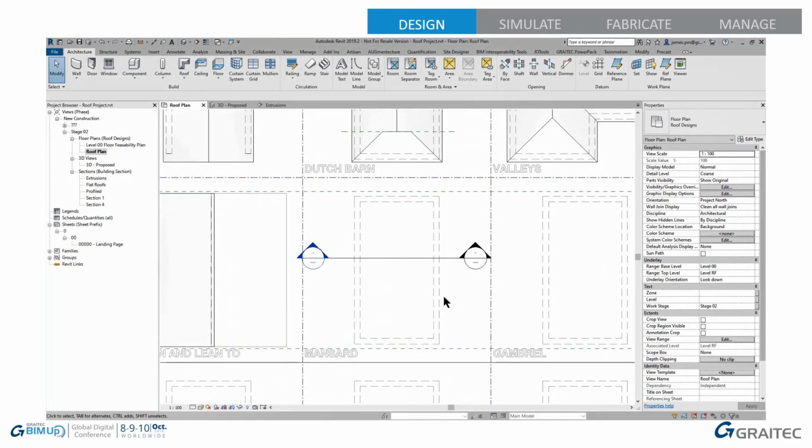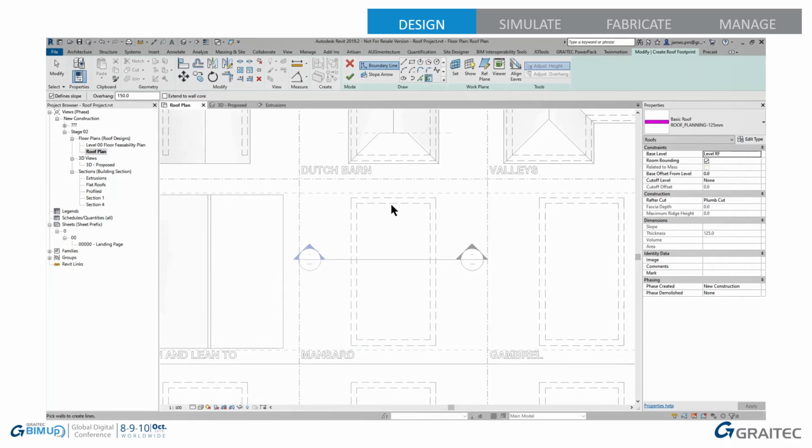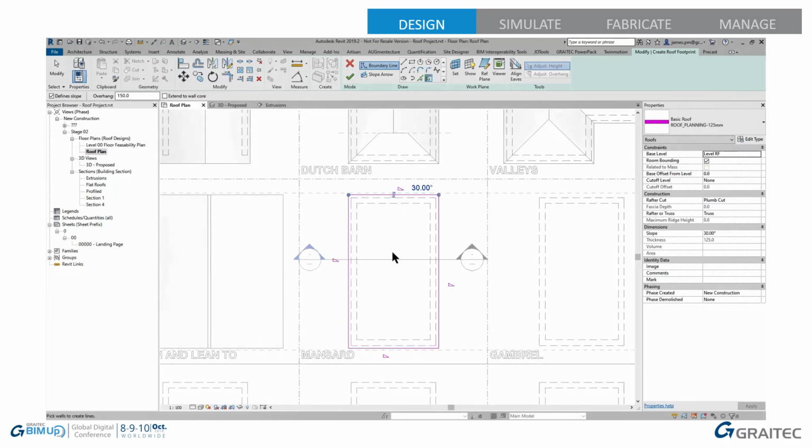And now let's look at our mansard roof. It's not my favourite roof to do in this, but there's a simple technique to do it. So again, we're going to do this in 2 roofs. I'm going to use a roof by footprint. I'm going to tell it what roof level it's going to go up to, start at. And then there's a setting in here.